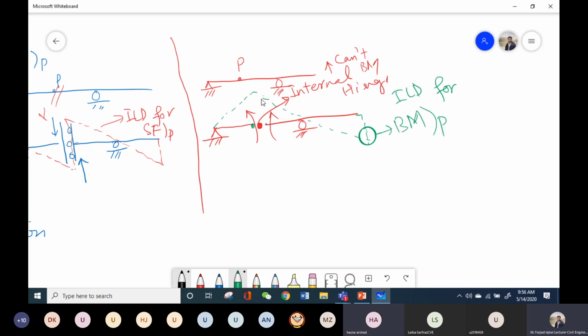It will try to move up basically. Let's say you are saying that it will go on like this. Do you think that it will happen in actual conditions? If you hold one beam from this point and apply a moment at this point, will it move up? No. Okay, sir. So this is how you get the shape.